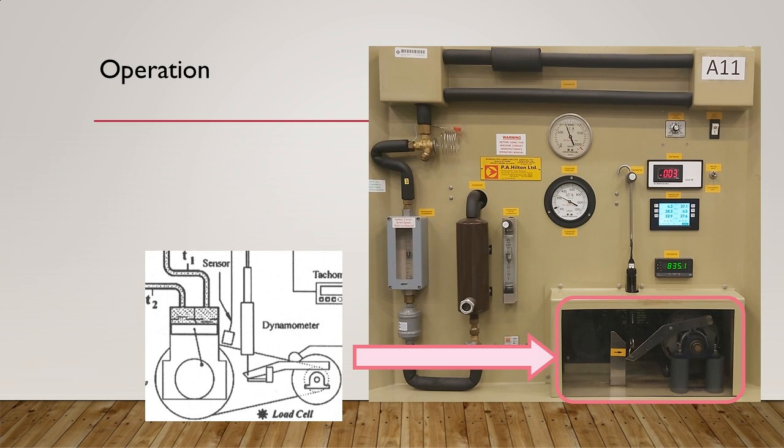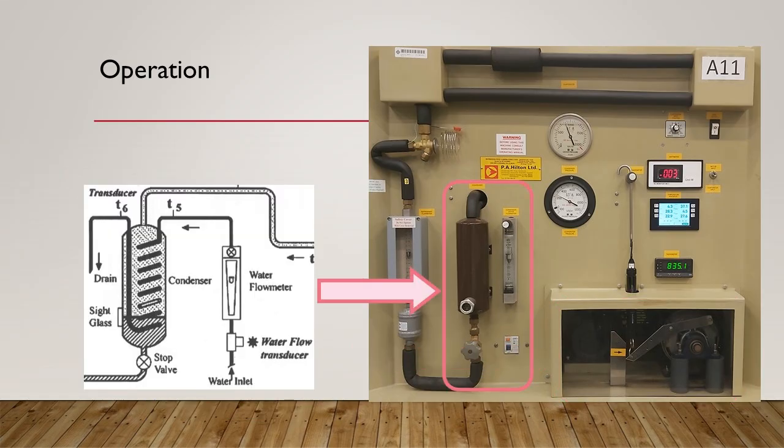The twin-cylinder compressor is powered by an AC motor through belt and pulleys. The refrigerant would be compressed and pushed to the condenser. When the refrigerant flows through the condenser, some of the heat energy would be absorbed and carried away by the cooling water.